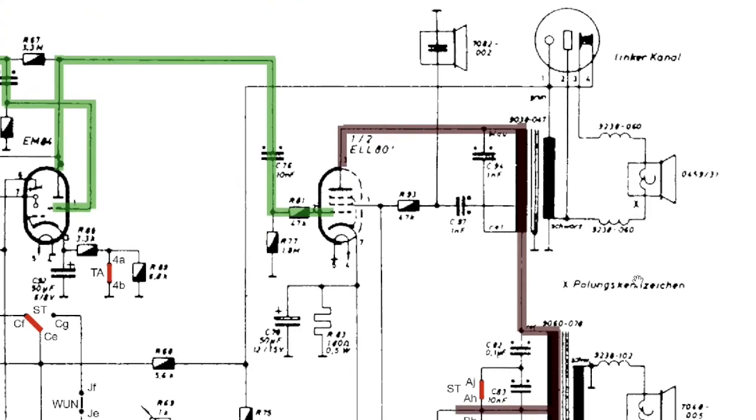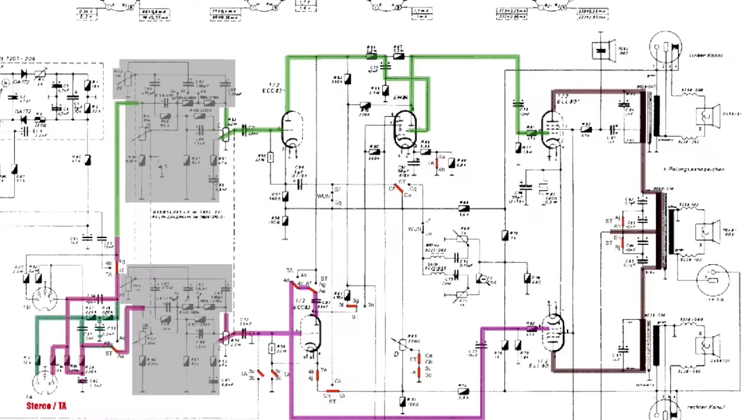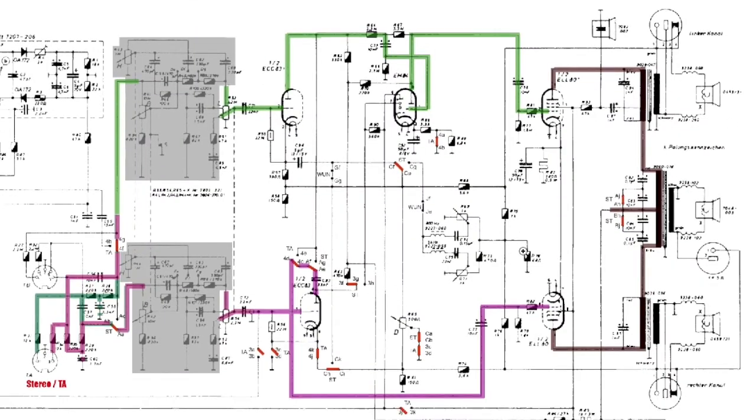The very high frequencies are the ones that are transmitted to this electrostatic tweeter. So this sound, this full range left channel, goes through there, the signal comes out here, through there, to the tweeter, which has been charged with B+ through this resistor that comes from that B+ line. And that's basically what we have. We have the full audio looked at in as much detail as I care to look at right now.